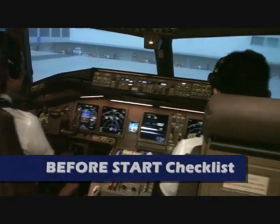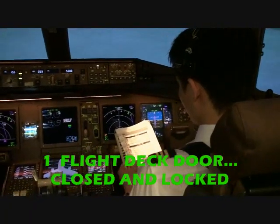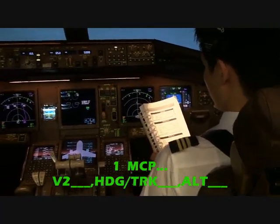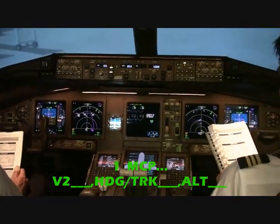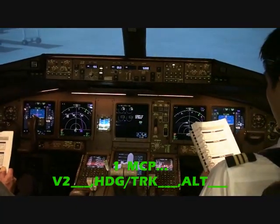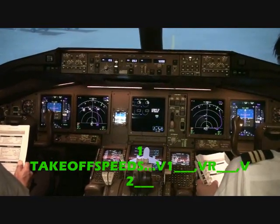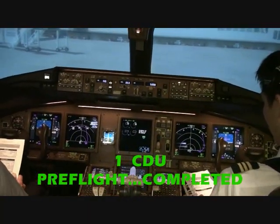Before start checklist. Flight deck door, closed and locked. Seatbelts on. MCP: V2 155, heading 053, altitude 5000. Takeoff speeds: V1 149, VR 151, V2 155. CDU pre-flight, completed. Trim.